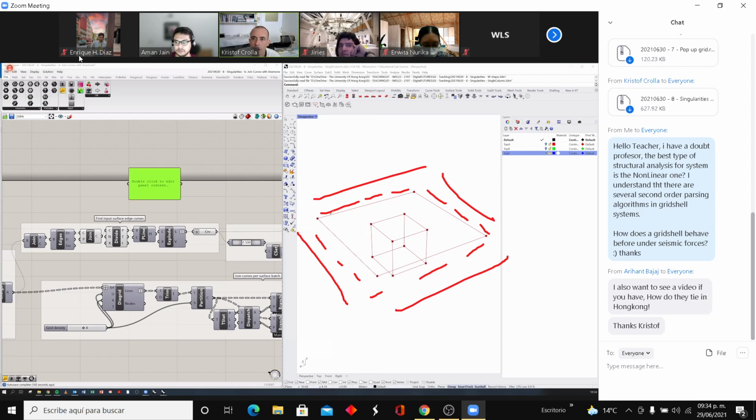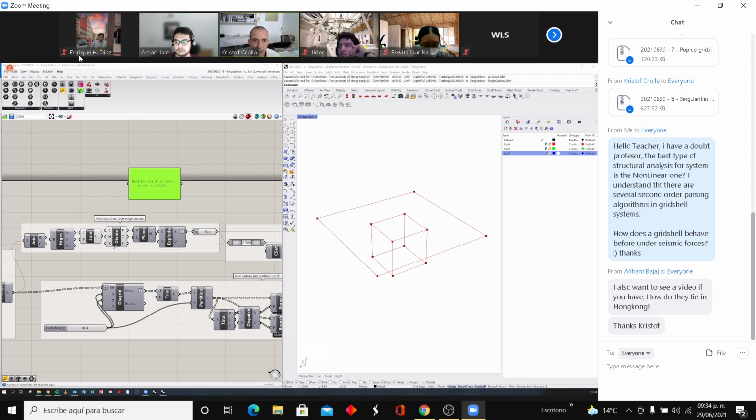So the way to do that is I'll take my continuous polyline and I'll only divide it at the kinks. So if you switch on your kink button there, and you divide it in 1, then it'll basically give you your corner points only. And then I can redraw a polyline through it, and now I have a polyline that only has 4 control points. Then I can explode this one into its line segments, and what I have now is basically all my edges. Let me show you. Now I basically have my continuous edges for all of these as a continuous line.